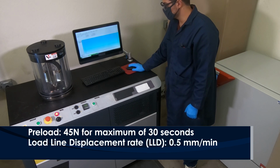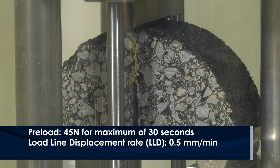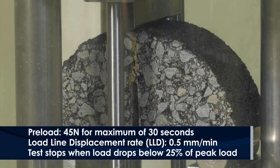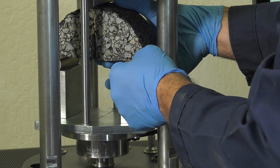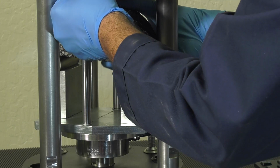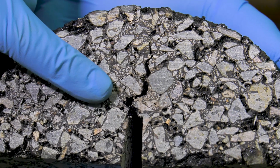Apply load to the specimen in displacement control at a rate of 0.5 mm per minute. Ensure that time, force, and displacement are measured and recorded at a sampling rate of 10 Hz or more. The test can be terminated when fracture failure occurs or when the applied load decreases to 25% of peak load. When the test is complete, remove the specimen. The process should be completed for each notch depth. The load and vertical deformation relationship at each notch depth is recorded.